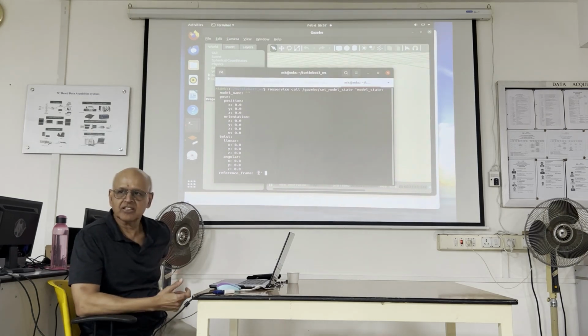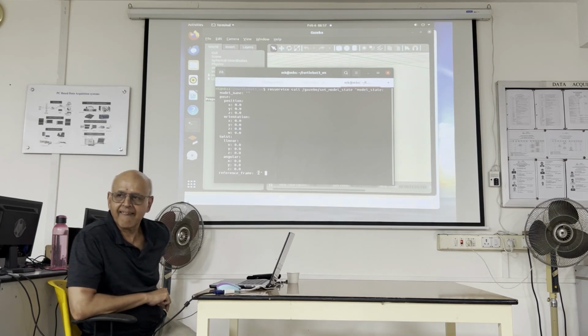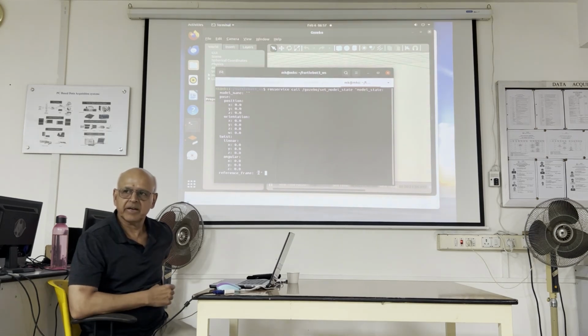So call is you're calling the service. Yeah, rosservice is working, I can do a rosservice call. But then I only call the gazebo GUI node. I cannot call the gazebo node. Nothing in the gazebo node. Whenever I try to call something in the gazebo node, it fails. But it does list the service. So I don't know why that is.